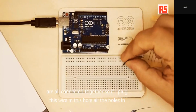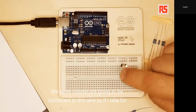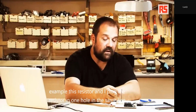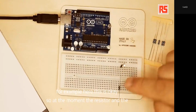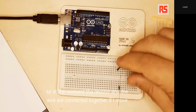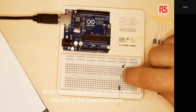So if I plug this wire in this hole, all the holes in the same column are going to be connected to this wire. So if I take, for example, this resistor, and I plug the resistor in one hole in the same line, for example, here, this is okay. So at the moment, the resistor and the wire are connected together. If I move this wire to the hole next to it, they are not connected anymore because only the wires in the same column are connected together.